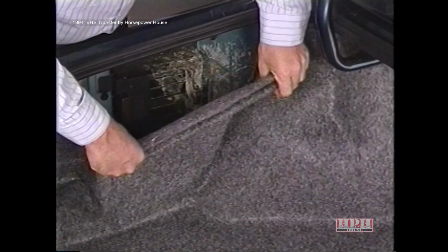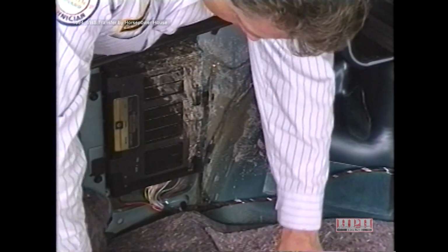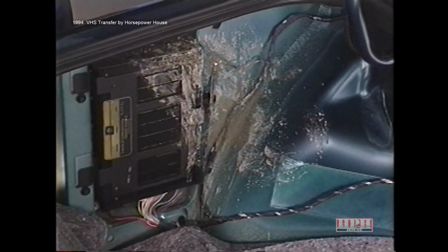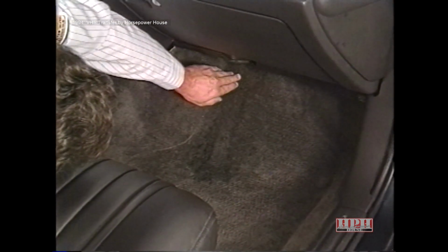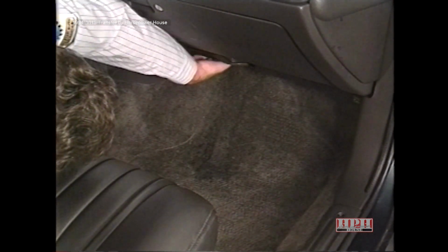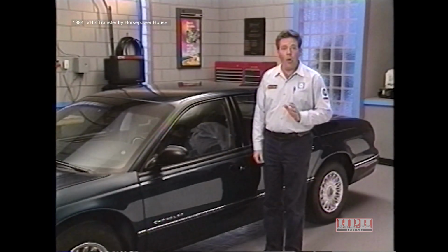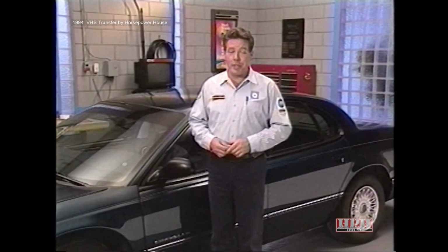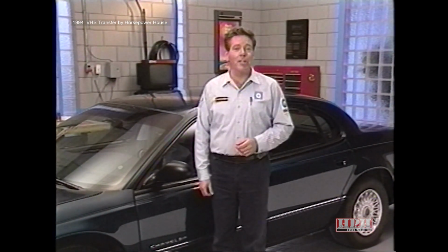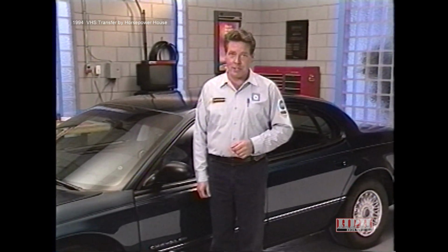You should also look for mud splash inside the vehicle. This is a good indicator of a water leak that may only be present under certain conditions, such as when traveling at highway speeds. Finally, remember that not all signs of water inside the vehicle will indicate a water leak. Problems with other components, such as an improperly positioned AC drain tube, may also leak water into the passenger compartment. Knowing where to look and what to look and listen for are important skills when it comes to water leak diagnosis. You'll also need this information to answer our next review question.